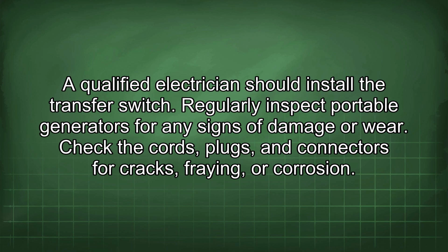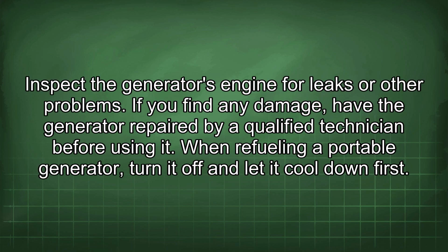Regularly inspect portable generators for any signs of damage or wear. Check the cords, plugs, and connectors for cracks, fraying, or corrosion. Inspect the generator's engine for leaks or other problems. If you find any damage, have the generator repaired by a qualified technician before using it.